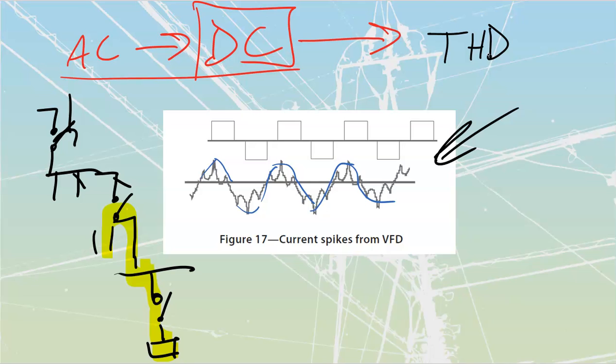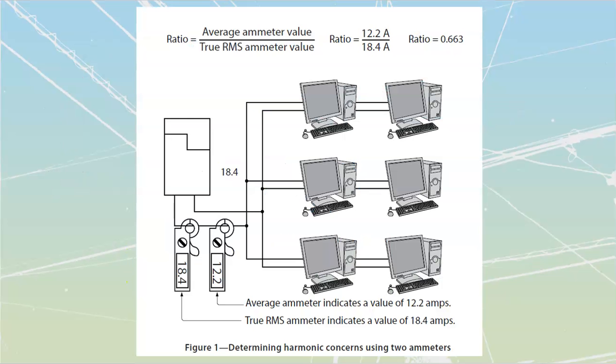You should be using a good meter for all of this tracing and locating. Particularly, you need to be using a meter that is true RMS. If your meter is not true RMS, which means root mean square, you're not going to be able to do basic checks on it. You're also going to need to make sure that your meter is rated for the proper category, right? The closer you are out towards the main service, the higher the category rating needs to be because there's a greater chance that you're going to be exposed to massive faults on the system itself.